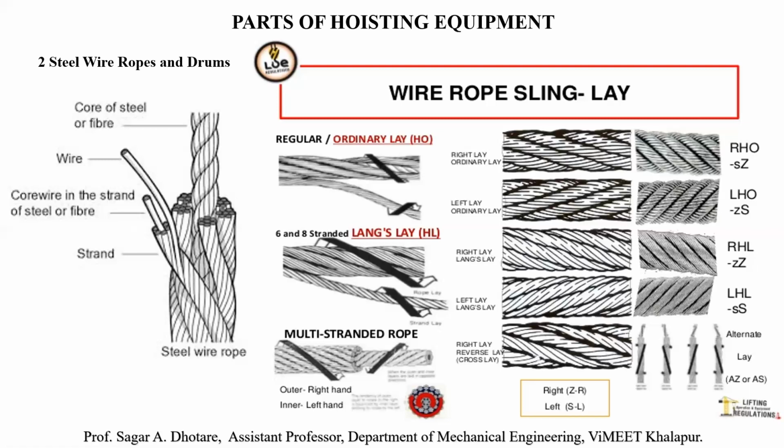What are the failure modes of the rope? Normally, ropes fail in tensile strength, and loading and unloading is often frequent. Then it can also fail in cyclic load, but tensile load is the major load.